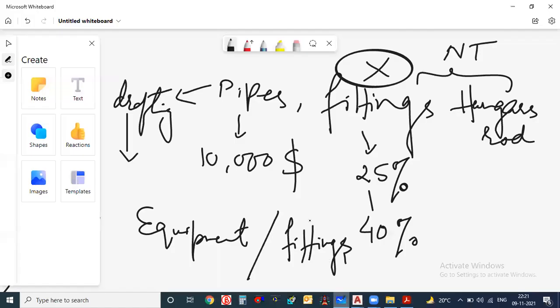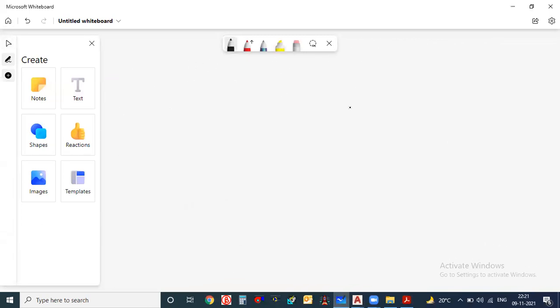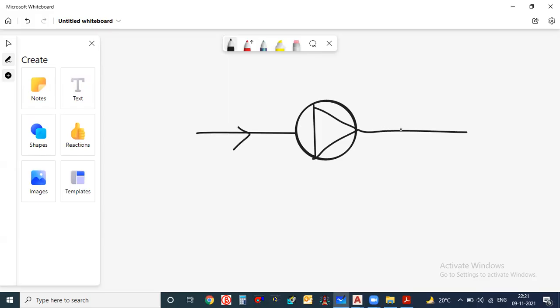Always remember this concept. We have two suction lines. Civil defense needs the water tank divided into two halves with two suctions. They will never accept one suction. Just understand this about suction and discharge: whenever the water is coming out of the pump, that will be our discharge.